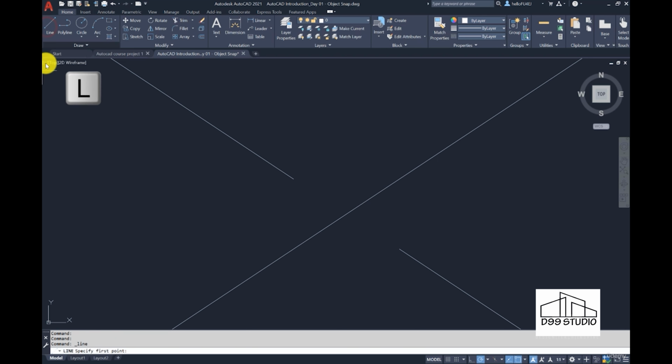We'll then select our line tool. And we're then going to click once at the end of the line and then move in the direction of the line. And you'll see that the line is extending and it's locked into the same angle as the starting line. And we can continue on till we meet the intersection. Once we meet the point of intersection of that line, we'll click, and that's our extension line drawn.